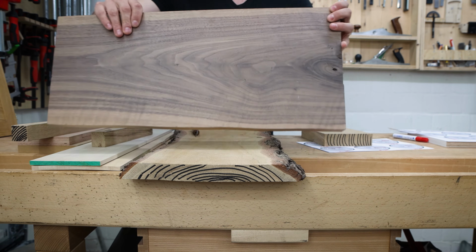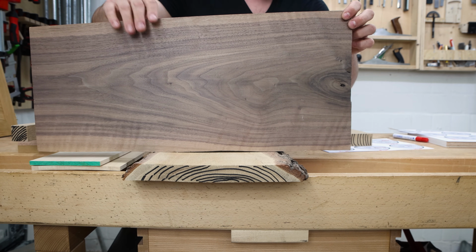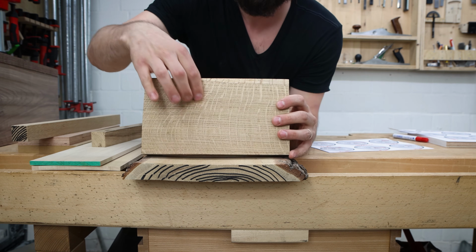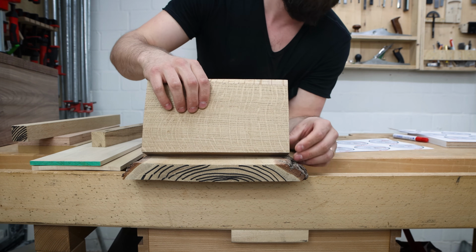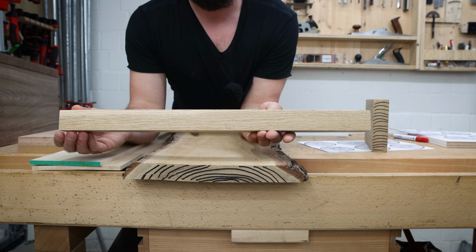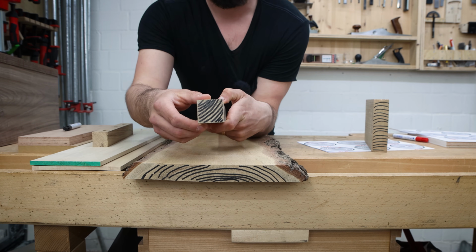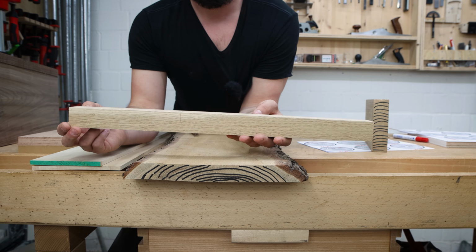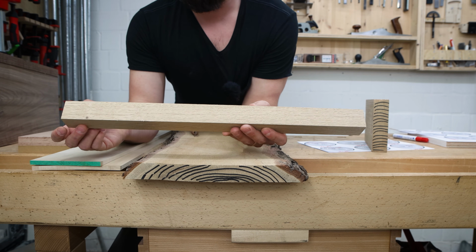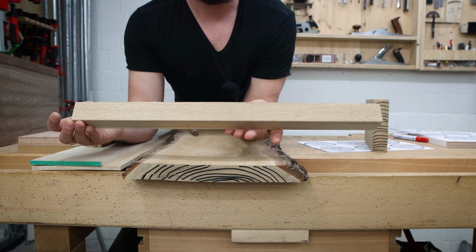Sometimes you can also tell from the face side which kind of cut it is. If you see these cathedrals, it's definitely a flat sawn board. On some wood species, you might see these ray flags. If you see ray flags, that is most likely a quarter sawn board. And on a rift sawn board, all 4 sides have the same grain pattern because all growth rings are coming at an angle of 45 degrees. This makes rift sawn stock perfect for table legs or chair legs because you don't have the cathedral on one side and a quarter sawn side on the other. You just have 4 sides that look the same.